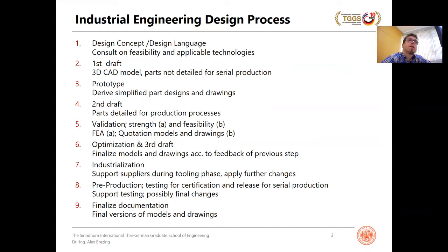like the parts. Now with CAD design, how do you usually work with 3D? Normally you feel you have to make part models first, right? And then put the part models into one assembly. That would be bottom up, right? But later on we'll discuss that more. Generally, it's a good idea to think in a top-down strategy. So keep the overall product in mind, the overall function, right? So top-down, break it down, then bottom up.